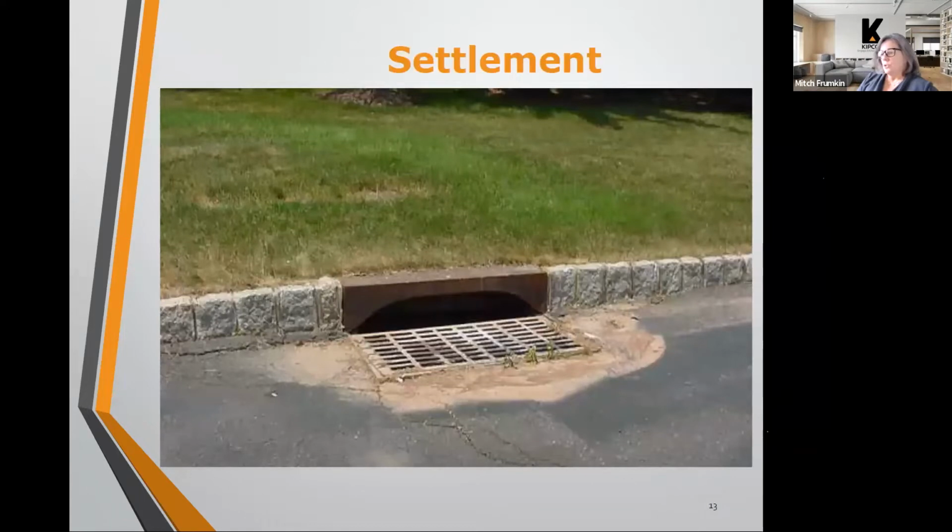This is another issue that is very, very common. There can be settlement around the catch basins in the roadway. And this happens because when they construct a community and they compact everything in the roadway, the area around the catch basins can be very difficult to get a proper compaction. It's not that the contractor necessarily has done a bad job in every case. It may just be that the type of soil that they're trying to compact is a little more difficult to compact around the outside of the inlet boxes.